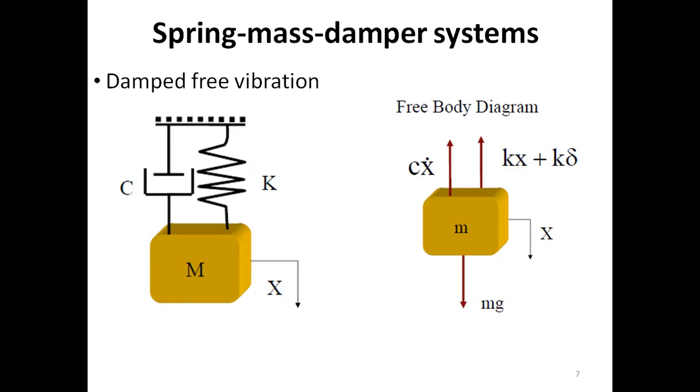And this is a linear vibration course. So in this we would consider that the spring stiffness is linear, the damper response is linear, and also, for example, the mass is not changing during the vibration. And so we have a mass, it is supported by this spring and this damper, and let's say at this instant the mass is moving in the downward direction, and this is the fixed support. So this is actually the lumped parameter model of a real system.